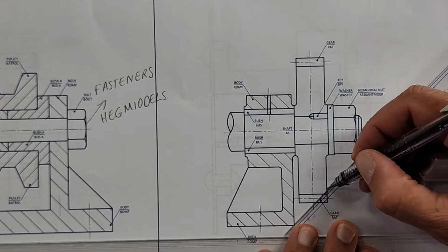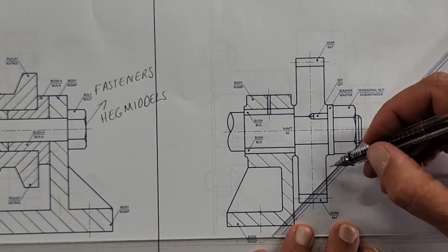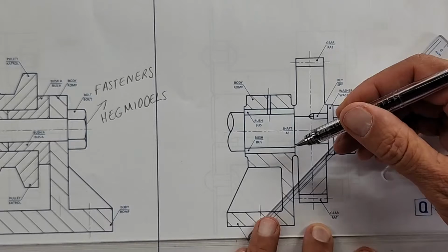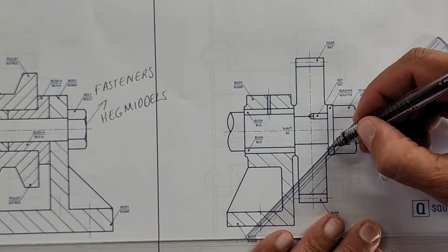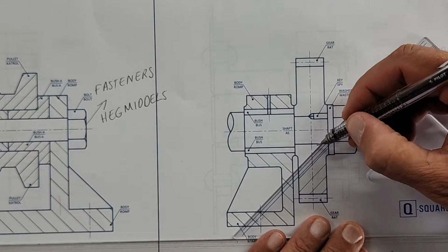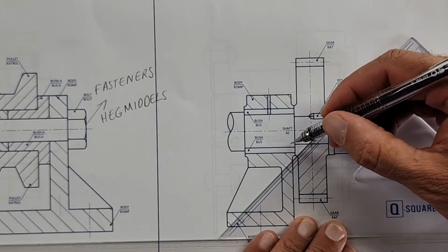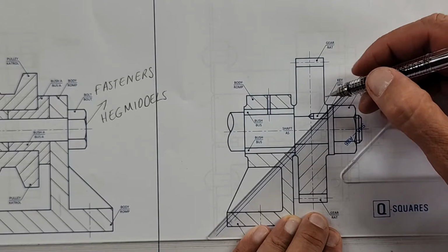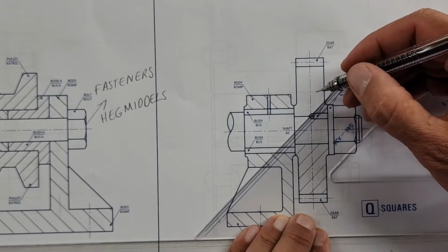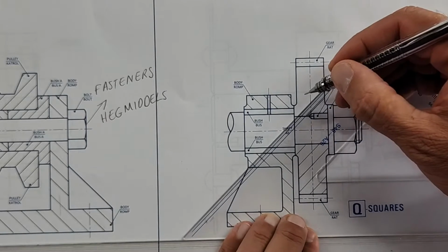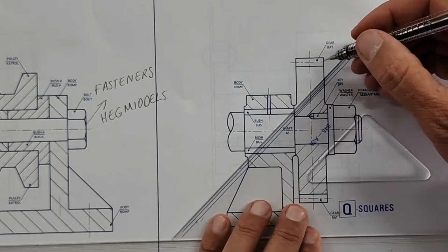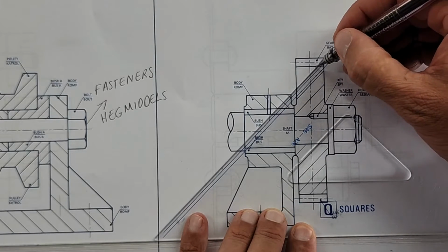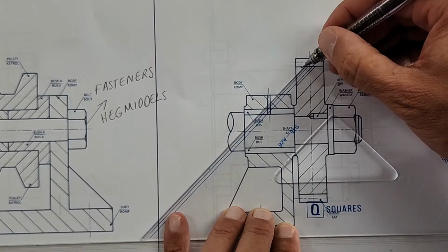We're going to use the same. We don't hatch the gear teeth. That's never hatched. This end here is the actual teeth part of it. So just the solid part of this gear we're going to hatch. Okay, and that's the convention for a gear. So you're going to draw many gears still in your drawing career. So please remember that the solid part of the gear, that part is hatched, this inner part, but the actual gear, the teeth of that gear is not hatched. Okay, so die tande van die rad word nie geharseer.